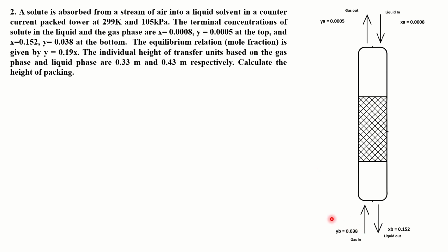The mole fraction of solute in the inlet stream of gas, which is YB, is given as 0.038, and the mole fraction of solute in the exit stream of gas, which is YA, is given as 0.0005. XA, the mole fraction of solute in the inlet stream of liquid, is given as 0.0008, and the mole fraction of solute in the exit stream of liquid, which is XB, is 0.152.